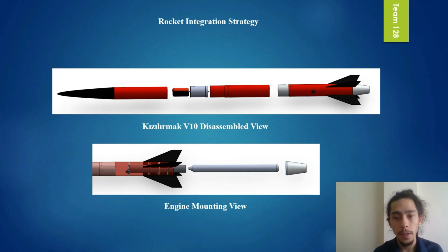These sections were fixed with 4 and 4 screws from the outer body to the bottom cover of the flight computer after the flight computer is placed inside the avionics section. In this way, the avionics section, the main parachute section, and the flight computer will remain integrated.